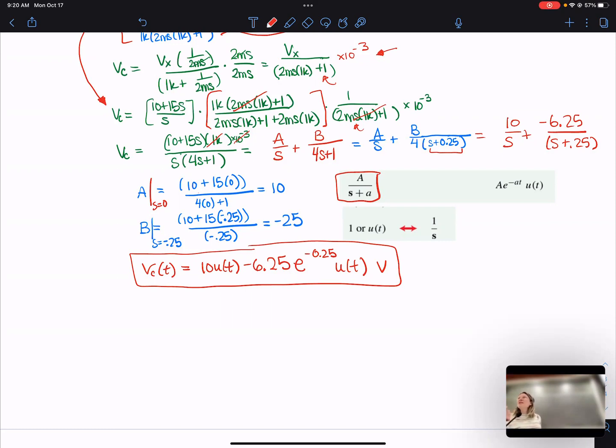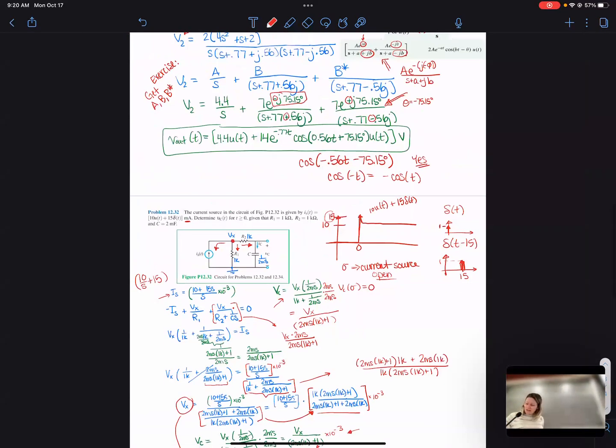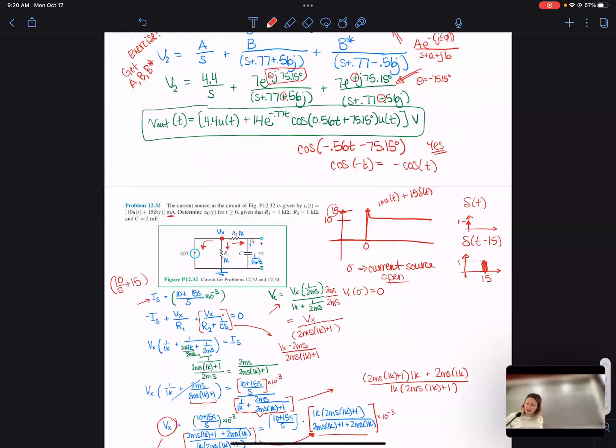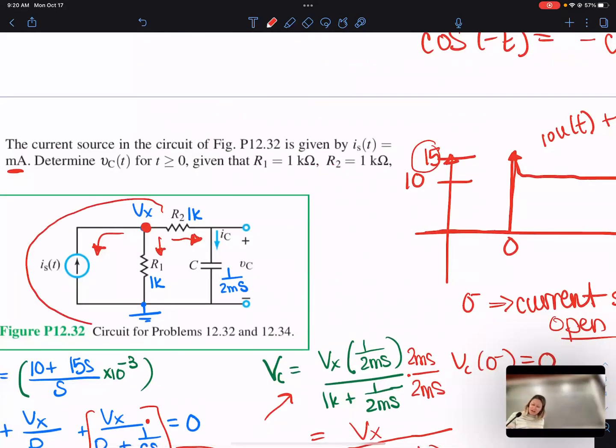We're able to get the same doing the... okay. All right, so he did the conversion of the IS of t and the R1 into a Thevenin. And so that should yield the same result. It might be a little easier algebra with all those. So whichever way you want to do it. I always like node voltage, so I tend to go that route.